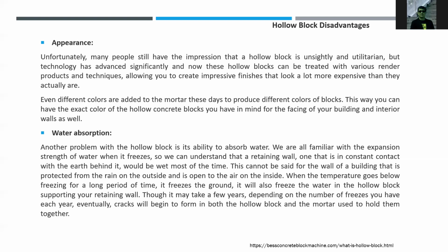In the United States, that disadvantage is the moisture because of the hollow blocks being porous. The water content of the hollow blocks will freeze during winter, and it will create a crack if it doesn't have a good waterproofing. Okay.